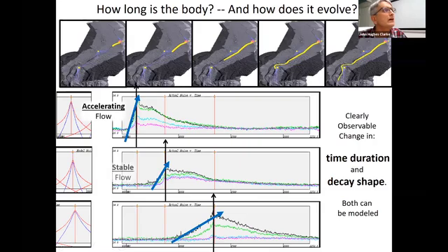And so what you see is each one of these, I can model the rise time. And remember, this one was too steep. This one was too shallow. To be too steep, you can explain that by the flow accelerating towards you. Remember, it starts off quiet because the noise it's radiating depends on its speed. So it catches up on you. So I can actually predict accelerating flow. Whereas out on the lobe, I actually know the flow is decelerating. It's like a bunch of drunks coming home after the pub. Shh, be quiet. And you get quieter as you get there because the velocity is dropping.